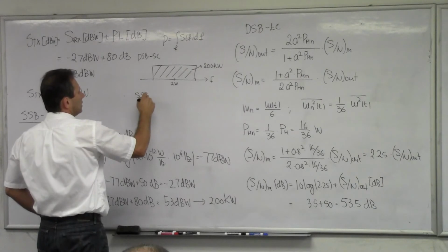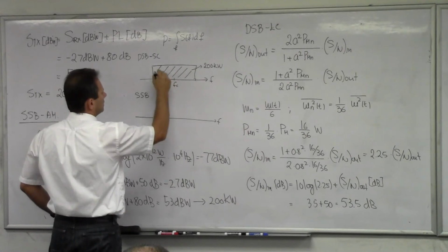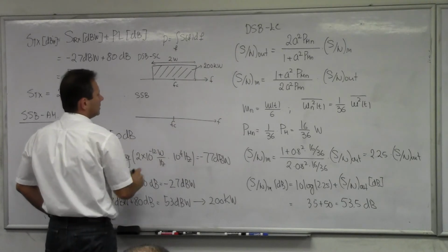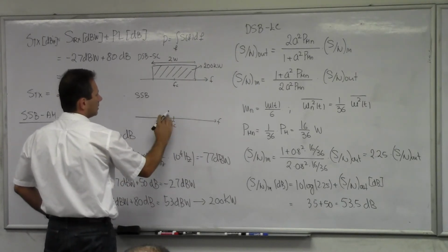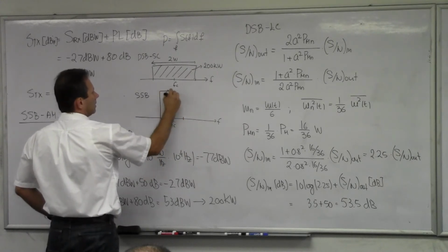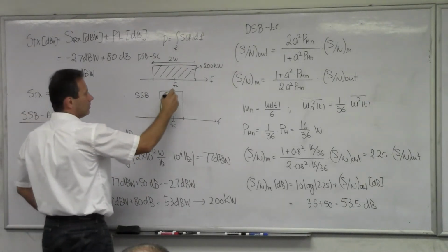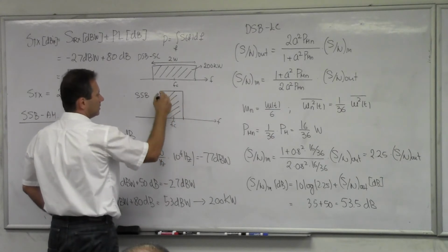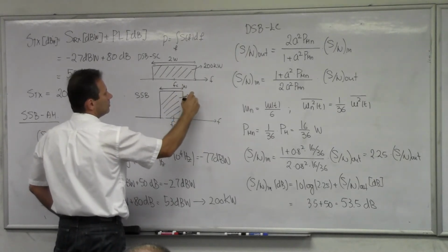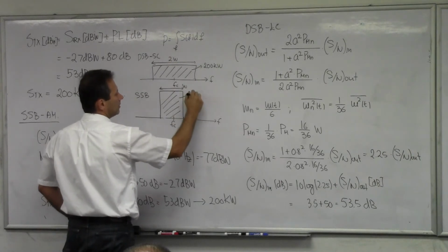For single sideband, how does this look? Here's your frequency. Now this is fc and this width is 2W. Now here's your carrier frequency fc, and here's your W, half, so this is W. Your total power needs to be the same. So the only way to make that is now this is W, so this needs to be 2 times S in this case. Double power spectral density.